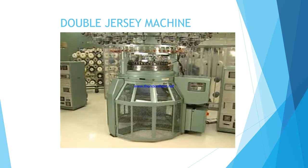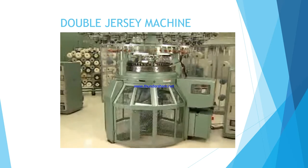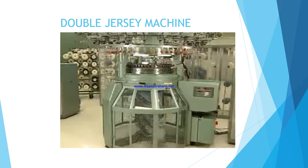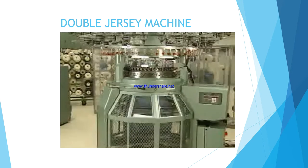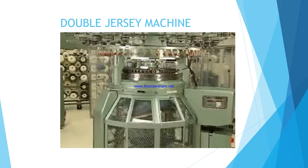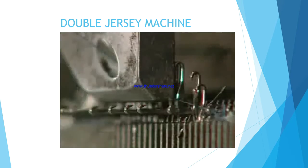Knit fabrics can be made on more than one set of needles. Unlike single knit fabrics, double knit fabrics are produced from two sets of needles. You've seen how circular machines can be used to produce single knits, but they can also be set up to create double knits. To accomplish this, a second set of needles is arranged in a dial above the cylinder. This dial has slots that hold the needles at a right angle to the vertical cylinder needles.